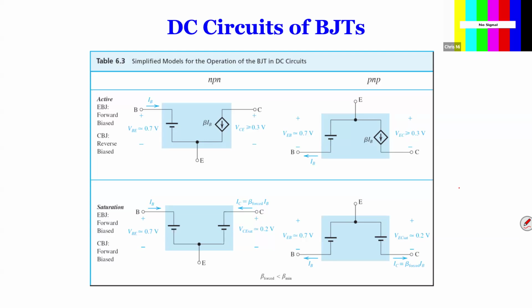And the switching mode, you're only going to do that when you get into 584, power electronics. They use these transistors as a switching device, which means it's either saturation or cutoff. They don't want the linear region. The reason they don't want the linear region is, for example, if this thing is carrying a small current. When you get into 430, you will also look at power amplifiers.